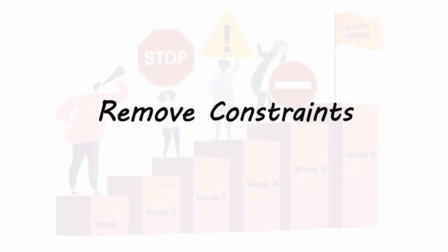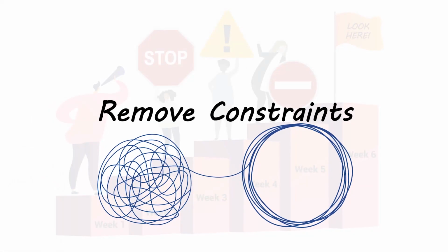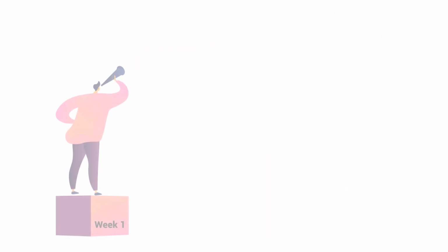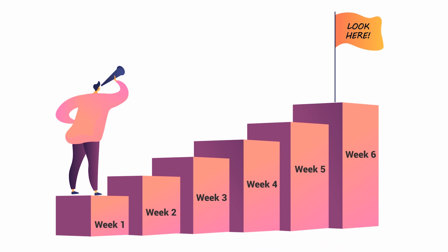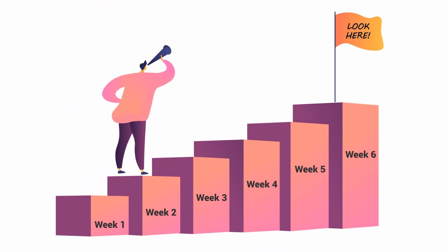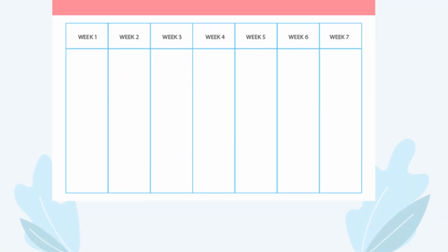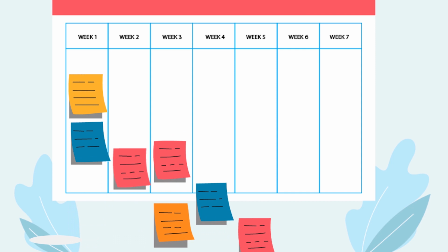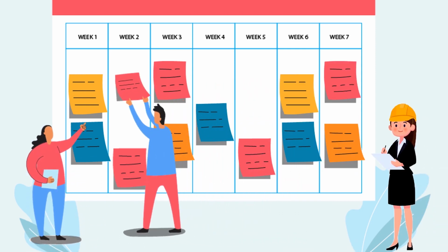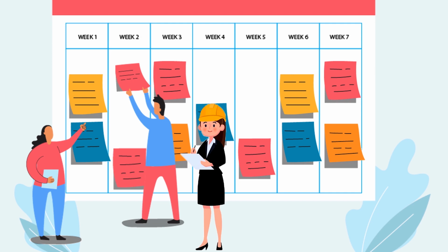As we identify our needs, we also discover constraints that can interrupt the workflow. This is why look-ahead planning is essential, as it aims to discover constraints and remove problems before they can even affect the project. Collaborating with all trades involved 6 weeks before the task can help create a seamless and reliable flow of work.